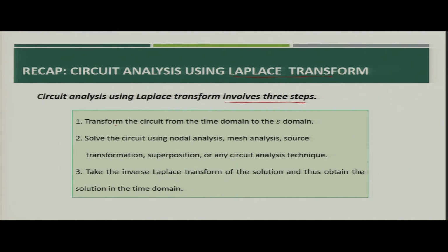First step was the transformation of the circuit from time domain into S domain, and then we solve the circuit using any circuit analysis technique, that may be nodal analysis or mesh analysis, source transformation, superposition, and so on. And then finally, the result we get is in S domain. So, we will take the inverse Laplace transform to find the solution in time domain.